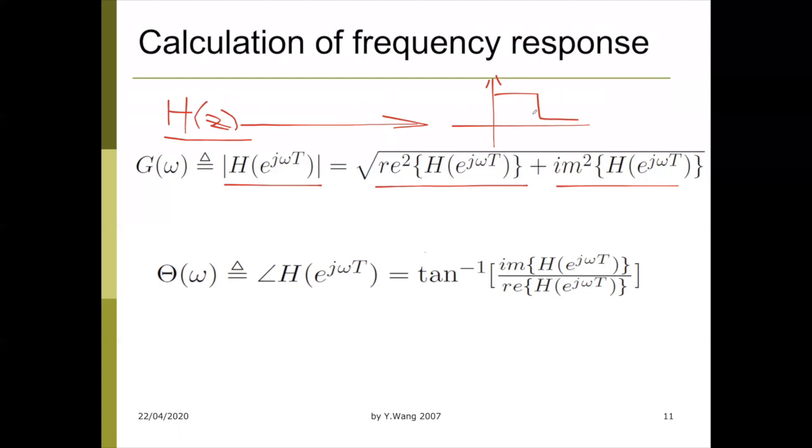But you probably don't use this journey quite often. You want a journey which is backwards. You normally say, I want a low pass filter, give me the digital filter. This is not reverse engineering, but the engineering approach. I want a filter that looks like this, a low pass, cut everything under 1K, and I want you to give me a digital filter. The filter design basically does this job for you. So we get this filter response and then we work out what the filter looks like.